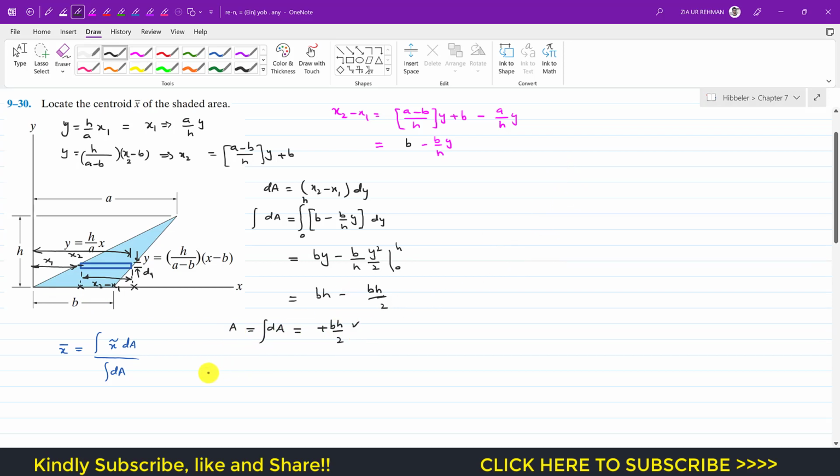Now the numerator is x tilde times dA. So first of all I will find x tilde times dA. x tilde is the location of the centroid of this differential strip from the y-axis. From here to here, this is x tilde, and x tilde will be equal to this x1 plus half of the length of this differential strip.